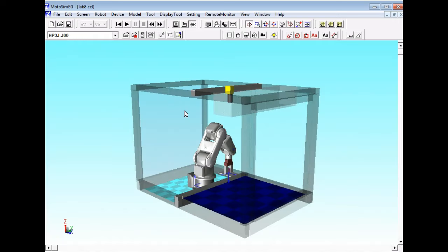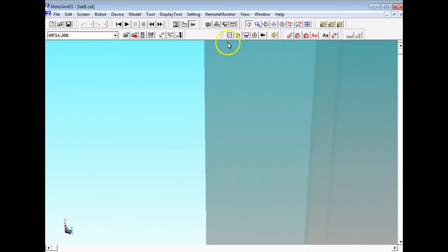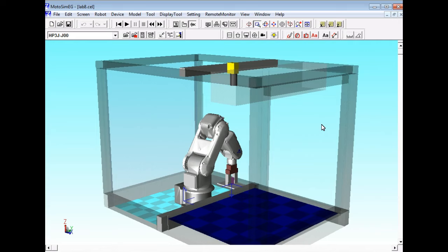This is a simulation. So this is the simulated work cell for the Motoman robot. So if you look over there, there's the Motoman, and here's the simulation. And what we would do with this is we would literally write our program doing the simulation. This is the same model, so when you do the simulation package, the simulation program provides all the models that Motoman makes. And then what you do is you create a 3D image of the work cell. Once you create a 3D image of the work cell, you place that robot in there. And then from then on, you come over here and you do your programming with the teach pendant. So I would come up here if I was going to do the program.